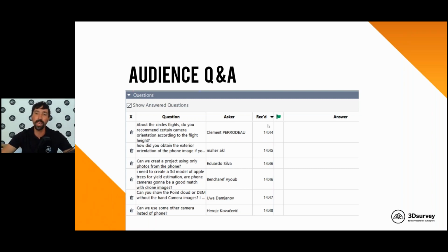If you have big fields, so huge projects, the RTK version is definitely a good decision because you need fewer ground control points for orientation and you get super accurate data. So yeah, definitely go and buy it. It's not expensive. You will probably do 3 or 5 projects and you earn your money back. Were you using network corrections for the RTK drone? Yes, in Slovenia we have a network of GPS stations, so you don't need a stick for the RTK drone.